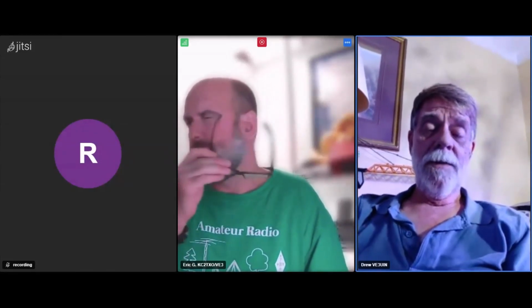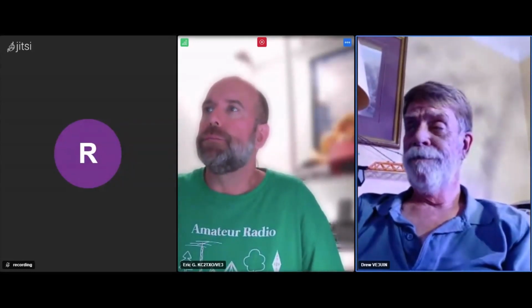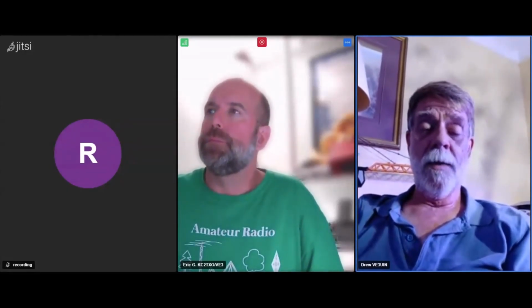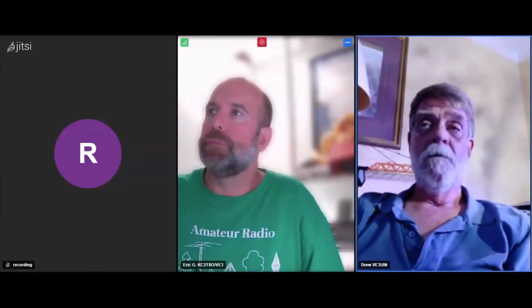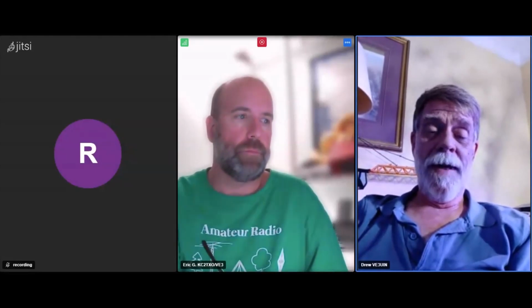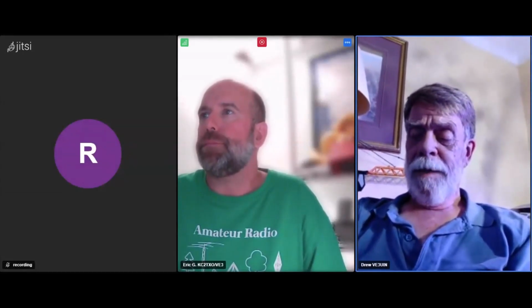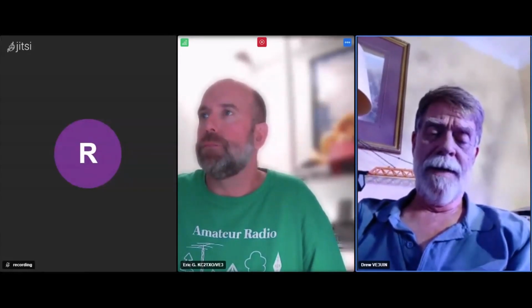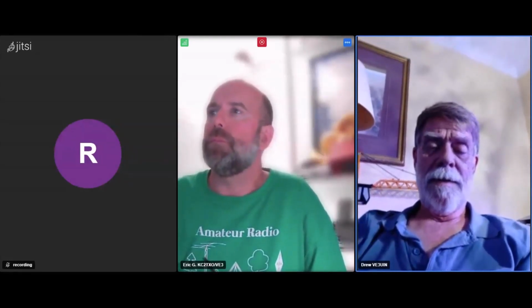And it looks really terrible. You look at this thing and it looks very, very homebrew. But it works like a champ. It's utterly matched at 20 meters and 10 and 15 and 6, and it has never moved. I basically made it out of speaker wire. So I don't put a lot of effort into this, but you might want to start with a straight dipole on 20 and maybe 40, and see if you can get them to work.